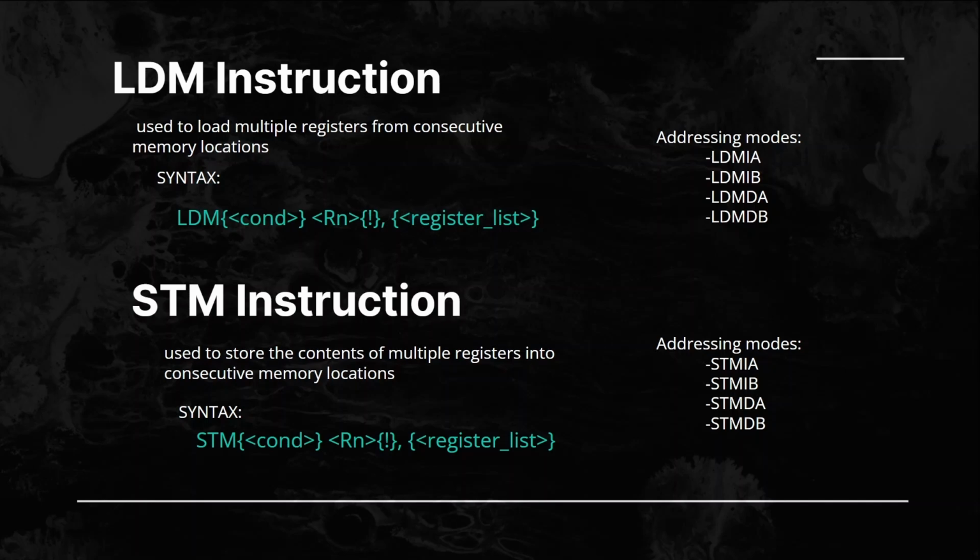Those modes are increment after, increment before, decrement after and decrement before. As you can see, this whole mnemonic means load multiple increment after. This is similar to the other 3 load mnemonics and the 4 store multiple mnemonics.